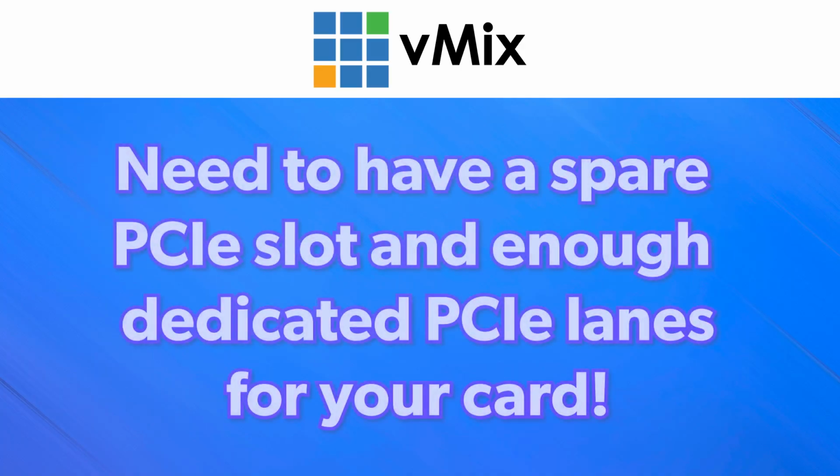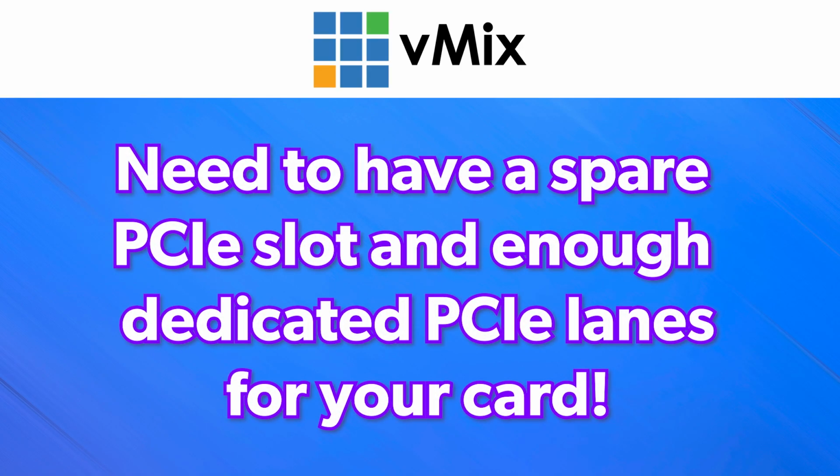Well, one of the biggest considerations for PCI Express cards is having enough PCI Express lanes on your motherboard. You need to make sure that you have enough available PCI Express lanes for the kind of card that you're going to be using. More and more motherboards are reducing their PCI Express slots and available lanes. A lot of them now just have a single slot for your graphics card and no additional PCI Express slots. PCI Express cards will list the number of lanes that are required, like by 4 or by 8 lanes, in order for that card to work properly.